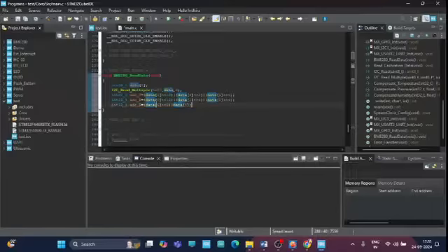That's it. So these variables store the raw data for temperature, pressure and humidity respectively by combining these multiple bytes. And after this again, float temperature is equal to compensate temperature ADC_T. So likewise we need to give for the remaining two.